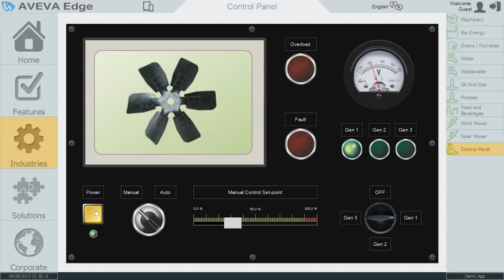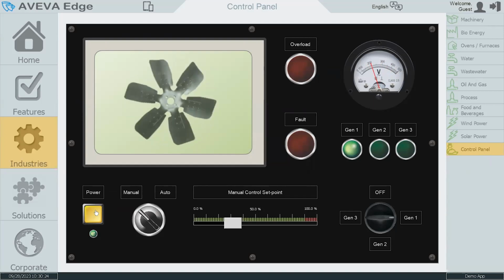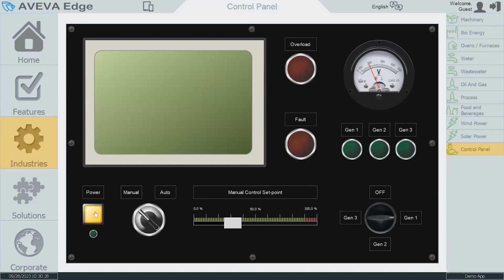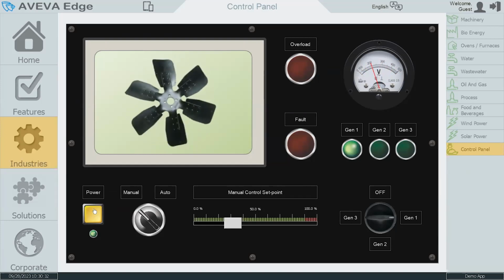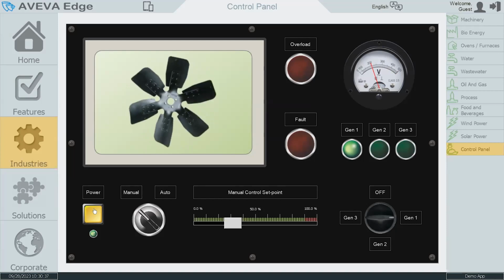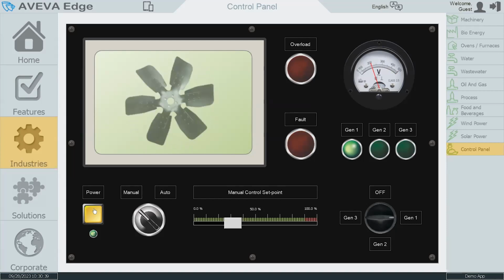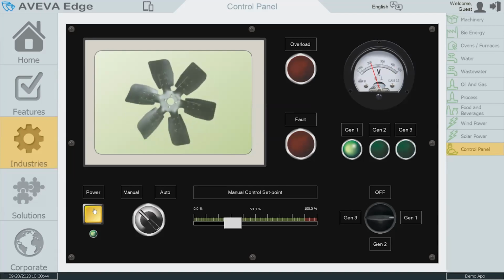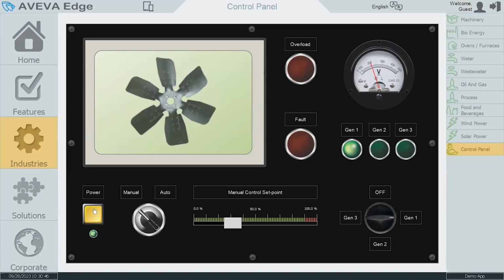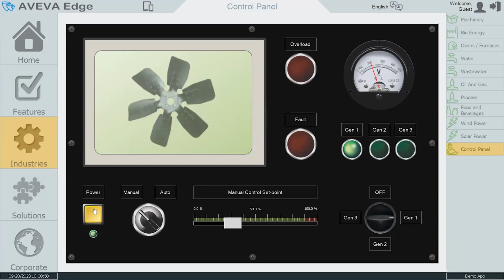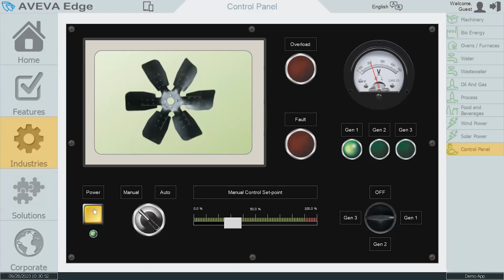We're going to simulate this in a few minutes, but just know that when you press the button, it'll simulate an on status. So the value in Modbus would be a 1, and the application would be running, or the motor would turn on, or the conveyor would turn on, or you open a valve or something like that.